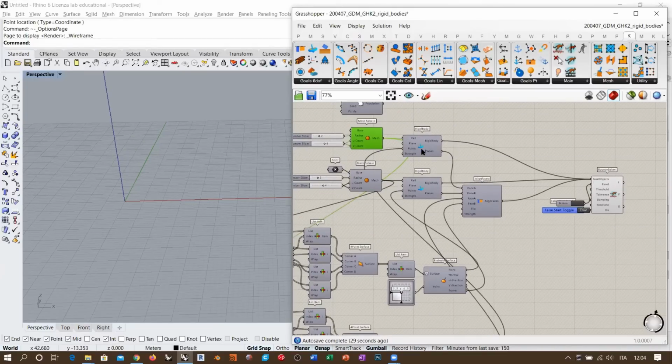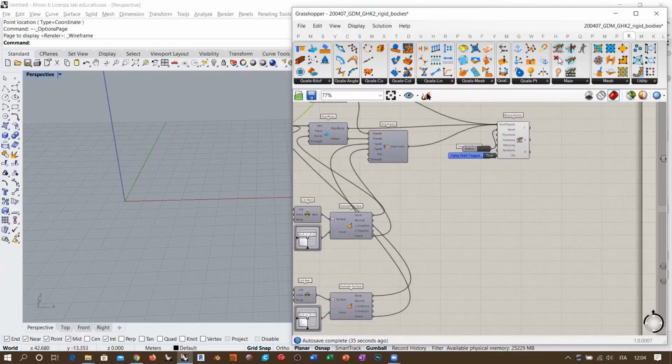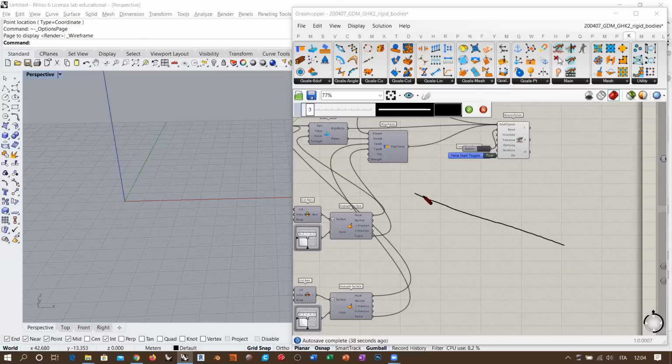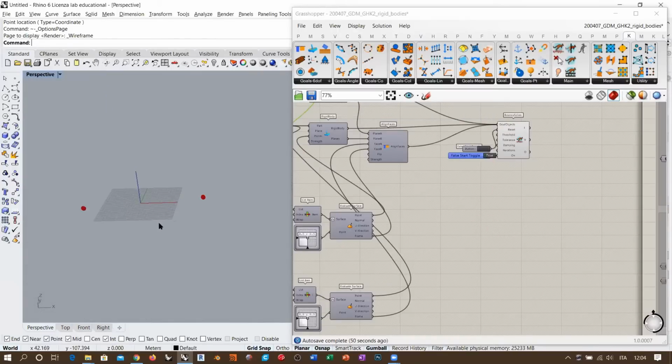Now, as the point is coincident with the face, there is a rigid situation where we have a face that cannot deform and a point that is a rigid point. It cannot be coincident with this face, because in a rigid body, two parts cannot be coincident in the same point in space. So that's why Kangaroo is trying to reconcile this position, and therefore it starts to separate the object in an elastic way. So you saw that the object started bouncing around. This is the solution that Kangaroo starts to implement, okay?